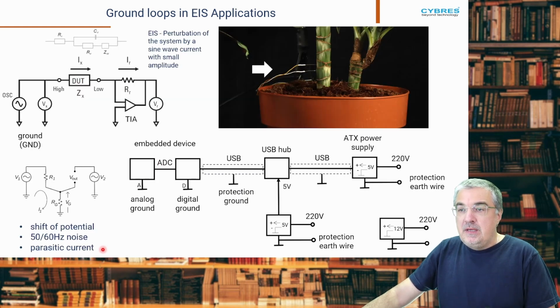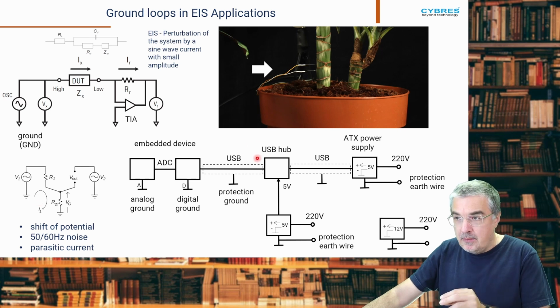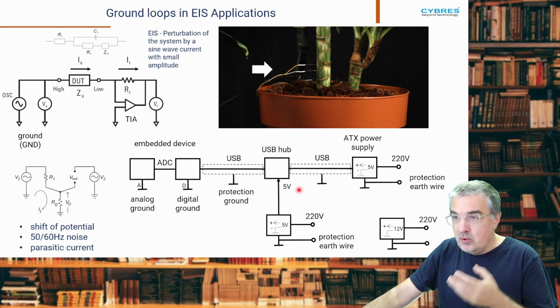The last problem appears only in seldom cases, if one of these power supplies is of not good quality. This current is of high amplitude. And if you put in some additional element that exactly produces this high current, you can experience, for instance, burnout of some COM port, or you can destroy some element here, or you can destroy USB hubs.